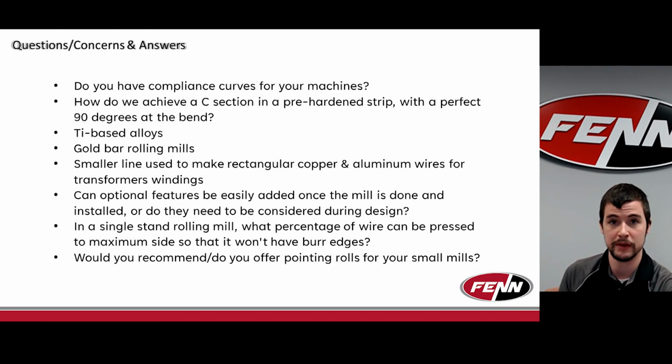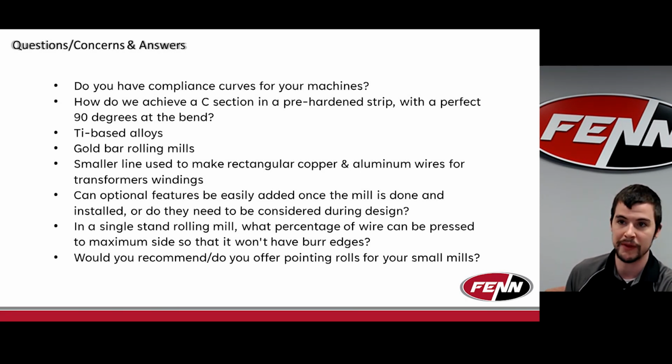One of the simplest ones to talk about is screwdowns themselves. Some customers have older mills with simple mechanical hand wheel screwdowns, and we've retrofitted them to be motorized or hydraulic, and have done full updated control packages, without doing too large of an overhaul mechanically on the mill.